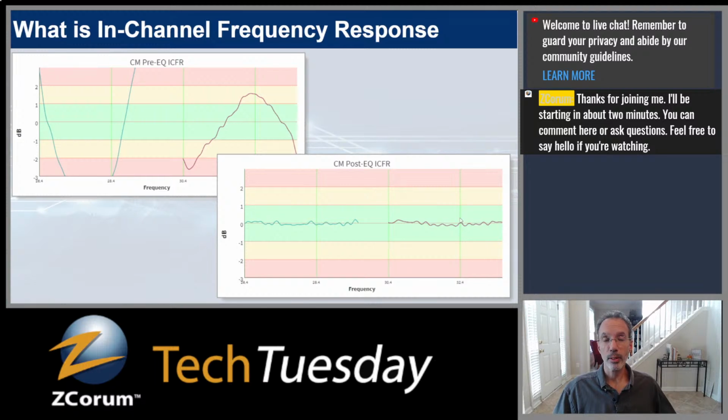It's right down the center of the line. So for this subscriber, they're not necessarily experiencing an issue. Everything should look fine for them because pre-EQ is compensating. But as I said before, that doesn't mean that there aren't all kinds of problems out in the plant, especially right here for this particular device, because this device is really having to work hard to adjust its signal, and it can only work so hard. So what you would really prefer would be to have really good RF spectrum on its own without pre-EQ having to do a lot of compensating. That way your modem's not having to work as hard, and you won't have to worry about this device or something in the near future getting worse, and then suddenly it goes offline.